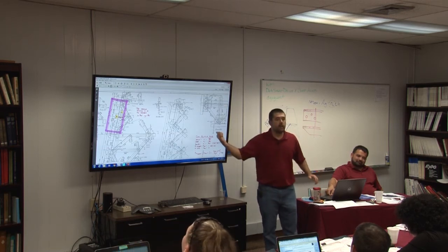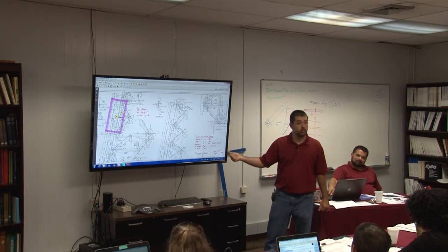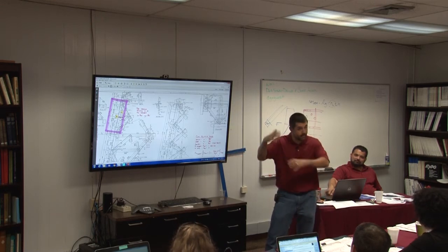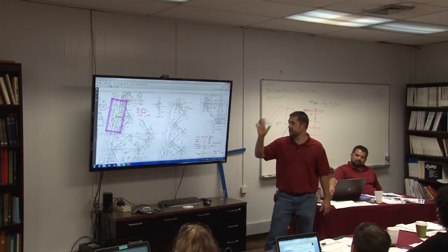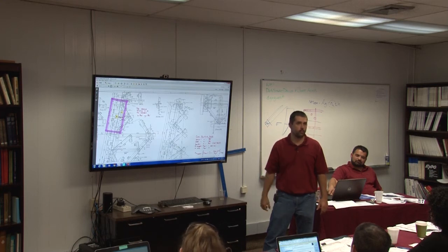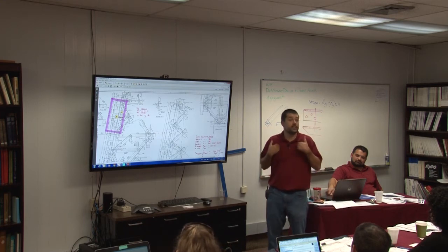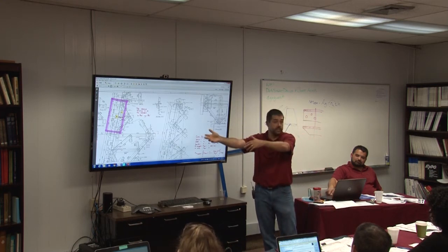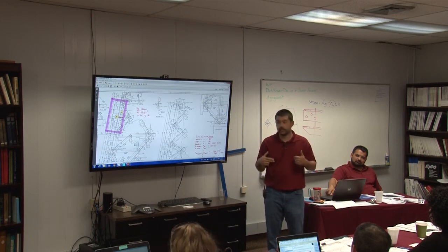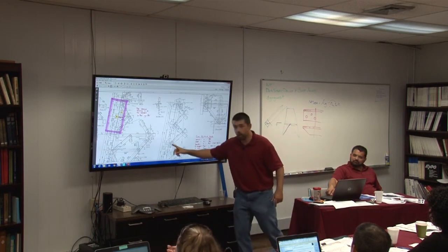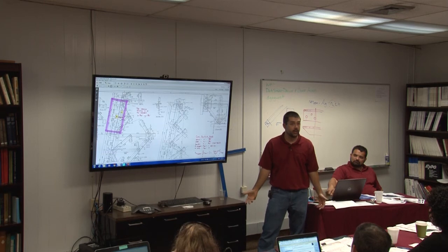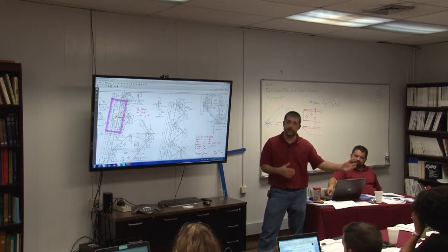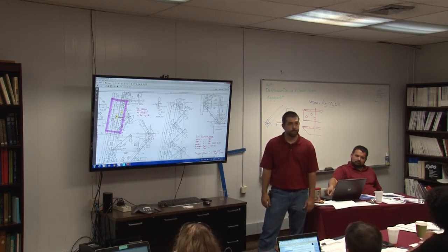Right. Yes. If I'm designing this new, I'm saying 4 bolts in my model. I'm sizing the member so that it can handle 4 bolts. But then if I'm the designer and I send it out for detailing and it comes back and the detailer has put 3 bolts in a connection here, and I think I've got to look at net section, maybe I've got to update. That's part of what you're hiring somebody to design a tower for. They've got to verify that the details match their assumptions.